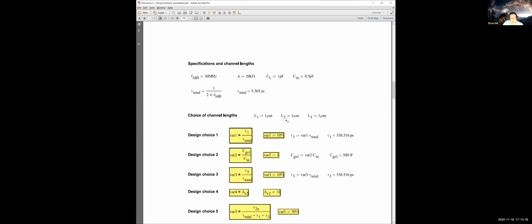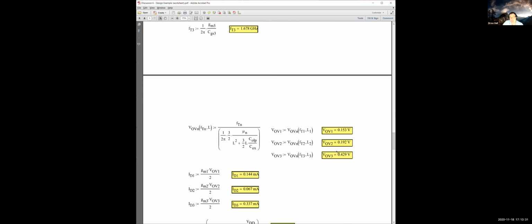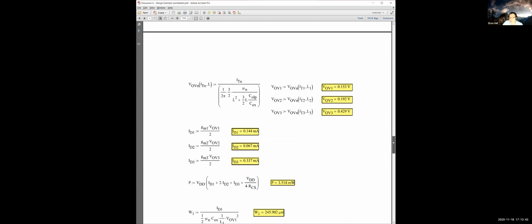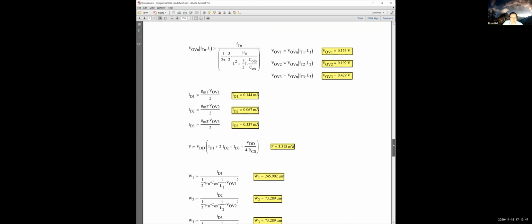If I had picked the channel length at 0.18, I would probably see that there are going to be some pretty significant differences here, because the short channel effects are going to start to creep in. So if you are seeing quite a bit of difference and you can't really rationalize it, one way is to look at short channel effects to try to explain part of your discrepancies.